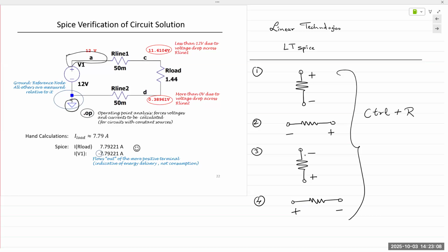I don't know if it shows up on a Mac or not, but in a Windows environment, once you're on LT Spice, if you hover your mouse cursor on top of this node, in the status bar at the bottom left corner of that window, it is going to show you this is node 001, and it'll tell you the voltage associated with that node. If you hover over here at the bottom, it's going to show you this is GND, this is ground. It's not going to tell you this is node 0. It'll simply tell you this is ground, and it'll say 0 volts.